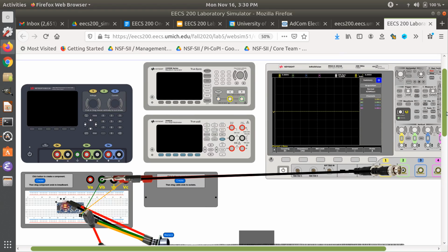That's still not showing anything. Oh yeah, we forgot to connect ground. So notice that there is some ability of the sensor to the system interface to notice if you've connected things up correctly, because I've got Spice running in the background to see how things are connected.